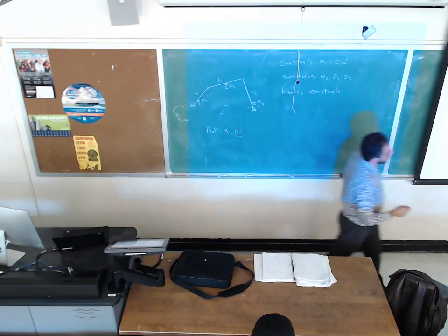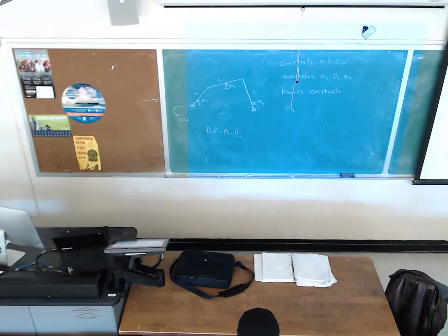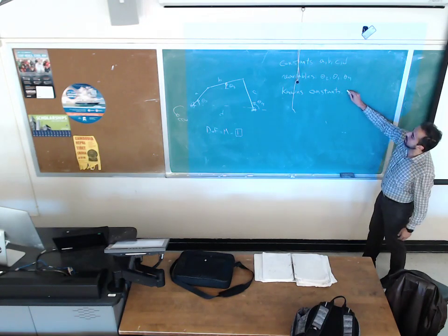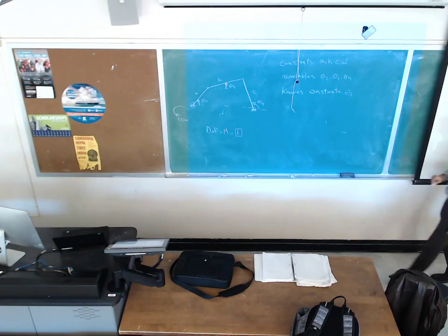So then you look at the variables. Depending on the degree of freedom, you should know the same number of variables. So since the degree of freedom is 1, one of the variables should be given. In this case, I assume theta 2 is known. Then I'm going to solve for the remaining variables.